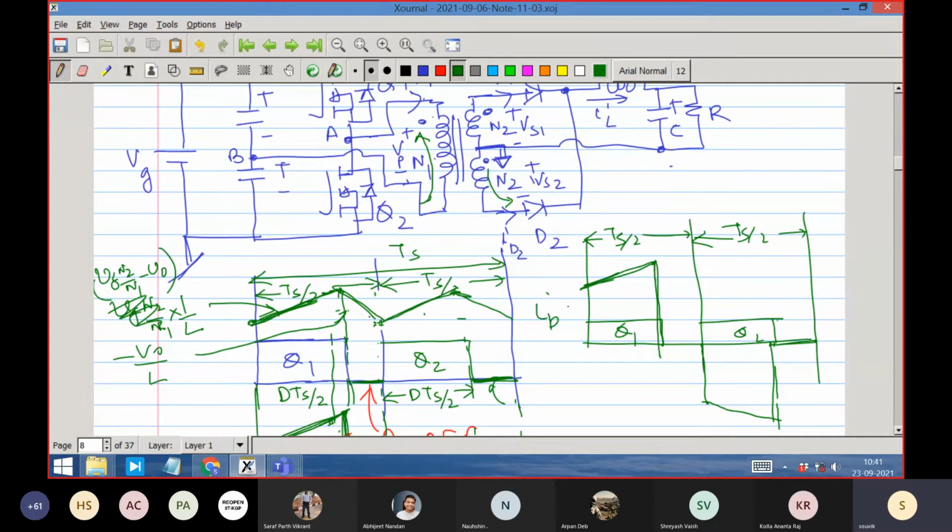I call IP equal to IP load plus IP magnetizing. Magnetizing I am not drawing. I am just saying the consequence of the current flowing in D2. This is where D1 is conducting, this one D2 is conducting, and load currents are MMF balanced, so dot-cross balanced. This is where from the cross the current is leaving.